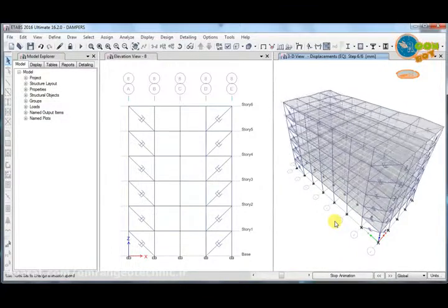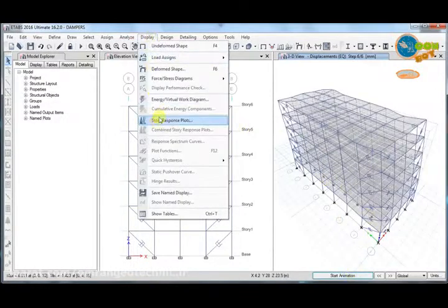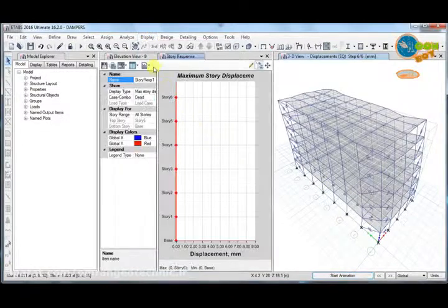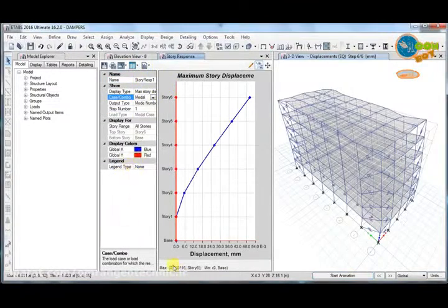You can see that it is trying to stabilize the building when it is applied with earthquake. You can see how much response reduction there is in the displacement. You can see very little deflection in mode 1. So the building has very little deflection, around 7 mm. It is very little deflection in the building due to this much of earthquake.